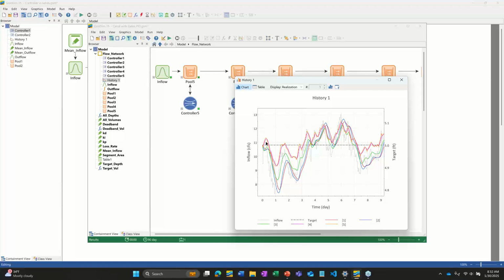And it also depends on the constants that you're applying to each one. In this case, the canal gets smaller and smaller as you go downstream. So your coefficients would be a little different for each one. But essentially, you could do it if you're simplifying the model in a way like this, just by simply putting a control at each pool and controlling them independently of each other. And that's the key really here.